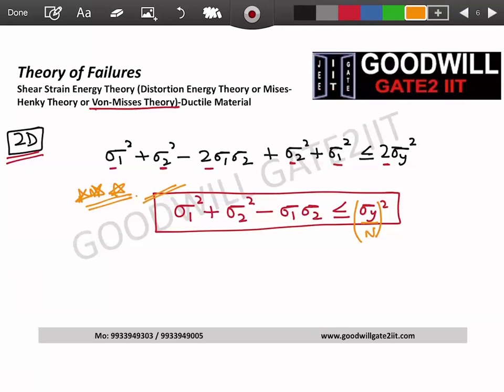What if you designed it like this? You say for these stresses, the weight on the aircraft should be, let's say, 1000 kg. But there are people who are stealing things, right? During the airport security check, you keep extra luggage in your laptop bag. You are allowed 20 kg and you take 21, and the person who is checking also says it's okay. Then you are in great danger, right? You said 1000 kg, but people are doing these things. So maybe during the flight your weight is 1050. Then if you design directly at yield, your system will fail.